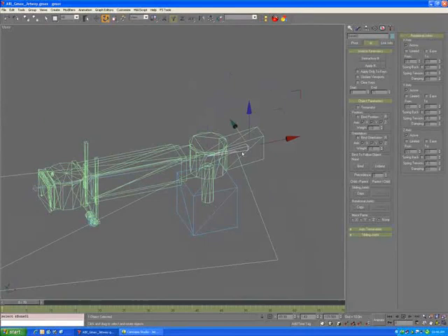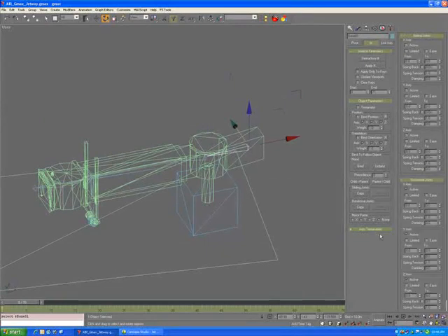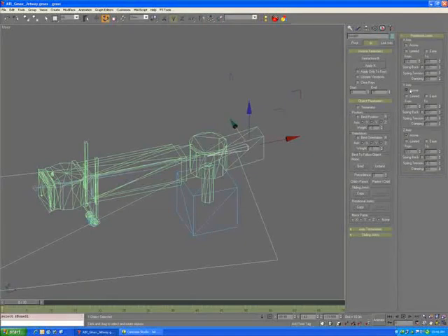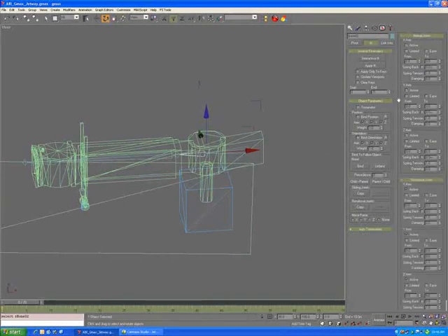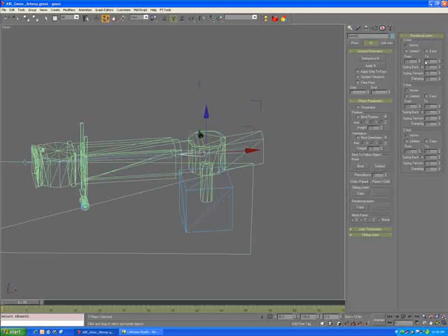So actually what we'll do is grab this guy to start with. This is the root one. You see there's sliding joints and rotational joints here. Well, we're just going to turn off the rotational joints, because this really should not move at all. This is the root node. It doesn't move anywhere. So then we'll go to the next joint. This has no sliding joints, and by default sliding joints are off. Since this has no sliding joints in it, we'll just focus on the rotation.